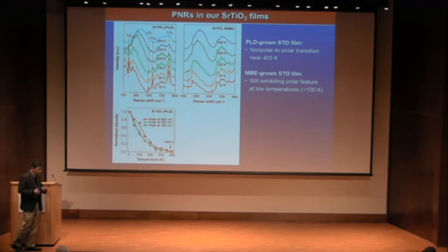And then in order to test the existence of nanopolar regions in PLD-grown thin films, we asked for films from Susan Stemmer's group at UC Santa Barbara, and they developed what they call hybrid MBE. They use a chemical source of titanium, the TTIP source, and control a much closer stoichiometry, which is very similar to the growth process for gallium arsenide.